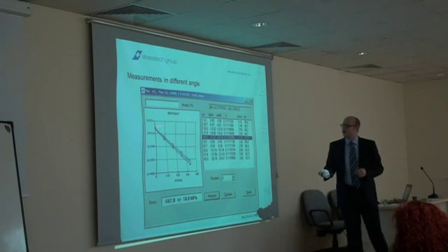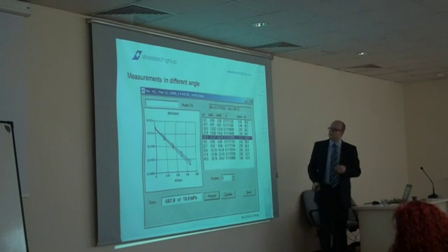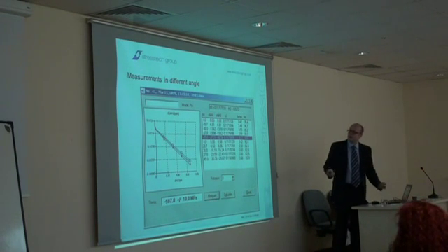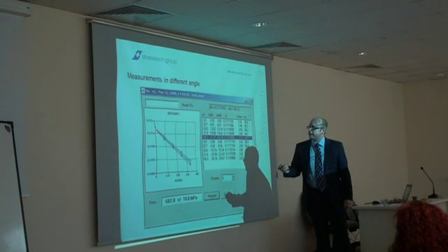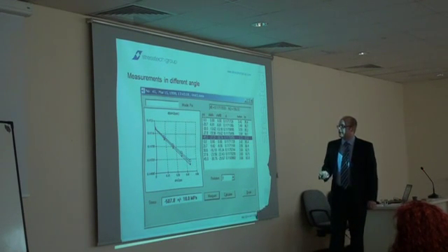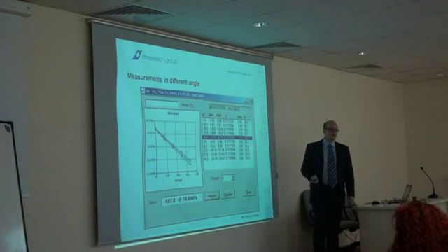And in our software, how it looks: here we have the D values which come from the peak shifts. And here we have the sin²ψ graph. Basically those are our tilt angles, but in the sin²ψ graph. And you can see from here that our D value is something like 0.117, 18 maybe, and here it is 0.11701. It's less here at tilt angle 45 than at tilt angle 0, which means that we have a compressive stress in our sample.